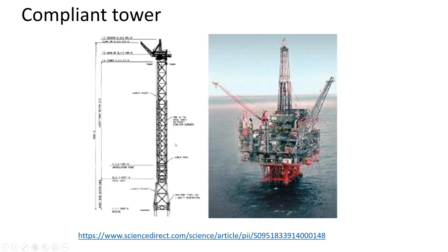This is a compliant tower. You see the base, this is the seabed, slightly bigger, but then the cross section is constant, and then typically you have some cables just to restrict the vertical movement, because this can be quite big. This can be 400 meters.